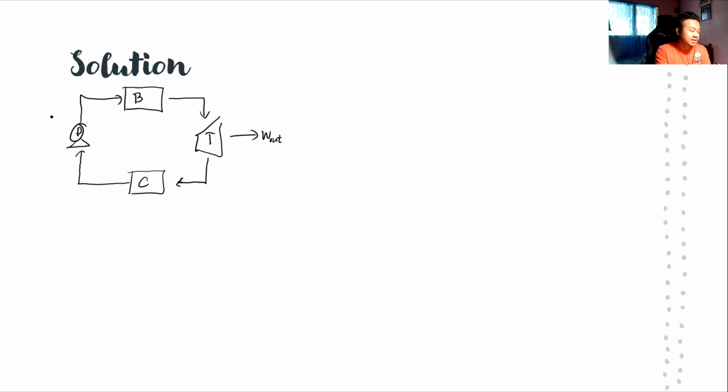So let's number our states here. So we have 1. It's actually up to you, but I personally prefer this numbering. So after the pump, it was said that it was at 5 MPa, 5,000 kPa, and the temperature is not yet known, but we know this is at 70 degrees Celsius, di ba?